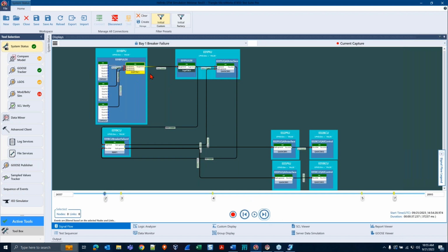Now, very shortly after, that distance protection unit is going to send out a GOOSE message and let the PTRC over in the PIU know that it should tell the XCBR to open and actually update the breaker position. And depending on your familiarity with 61850, you might be surprised that we do have PTRCs in both, but this was a design decision that was made over in Helix because the manufacturer of the PIU typically does use a proxy PTRC.